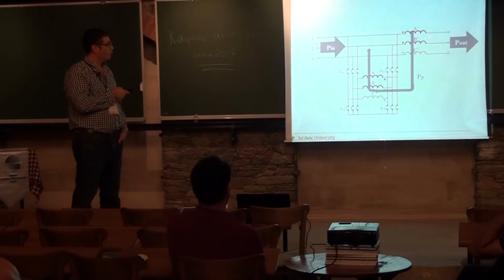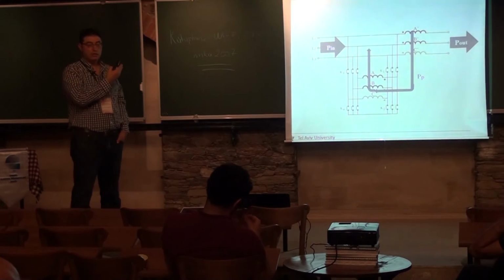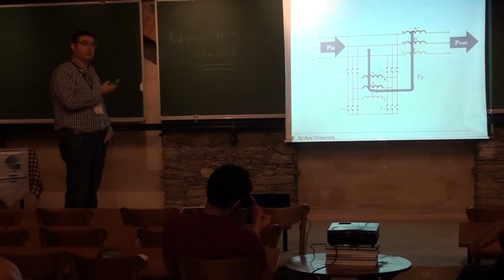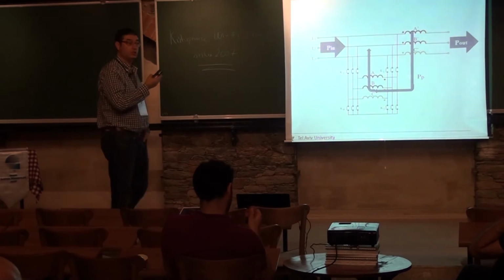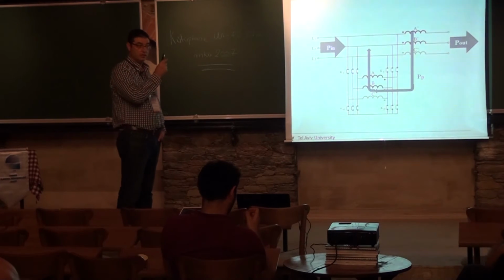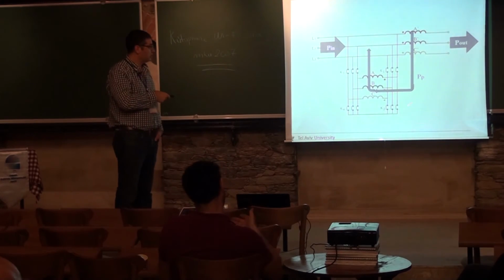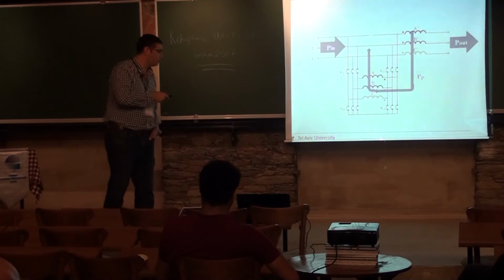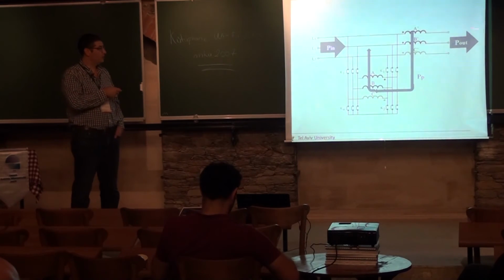But remember, when do we apply this? This is the highest voltage drop. We apply this when the machine is maybe loaded 20%, this 110 volts. So in practice, in the products that they sell, this transformer is rated at about 10 to 15% of the load power, which is nice.